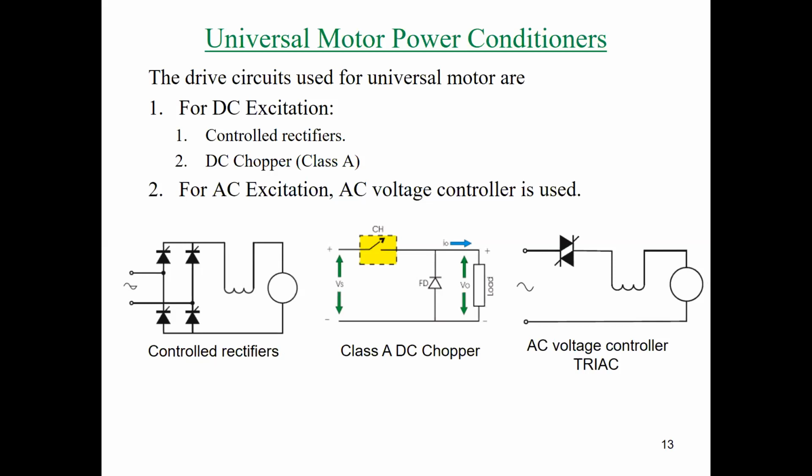Another important part regarding this machine is the control circuits. How can we control this kind of motor? For instance, you have in homes mixers and vacuum cleaners. And for high power machines, we said we can use this machine in trucks applications. So it needs a controller. For small appliances, we can consider any kind of conventional control technique by adding resistance, for instance. However, for high power machines, we have to use electrical drives.